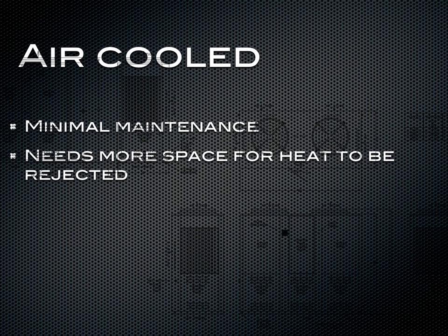There does need to be more space for the heat to be rejected to on an air-cooled chiller. Air-cooled chillers typically go outdoors. If you put them indoors, you want to make sure it's in a well-ventilated room. If you put it into a confined space, the heat will not be rejected and your refrigeration cycle will basically shut down and your piece of equipment will not get cooled.